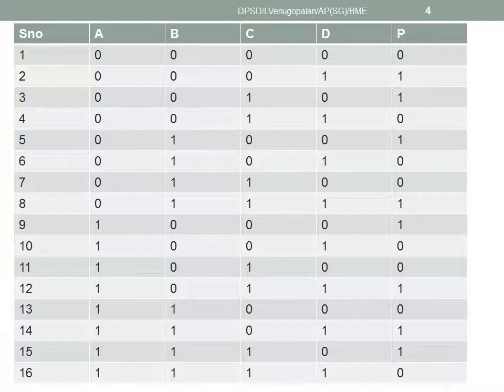Parity will be 0 if there is an even number of ones in your input signal, right? If there is an odd number of ones, then if I set the parity bit to 1, the whole signal becomes even. So we have to take the parity bit into account as well, to make sure that our whole binary digit has an even number of ones.